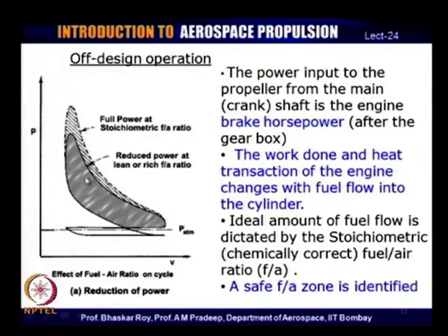That means the reduction of fuel air ratio and the increase of fuel air ratio has to stay within this safe zone, so that the engine continues to operate. If you go outside the zone, the engine could actually get blown out. That means the combustion process could get blown off, and the engine would stop operating. Hence, it is necessary that you stay within this fuel air ratio all the time during its entire operation.